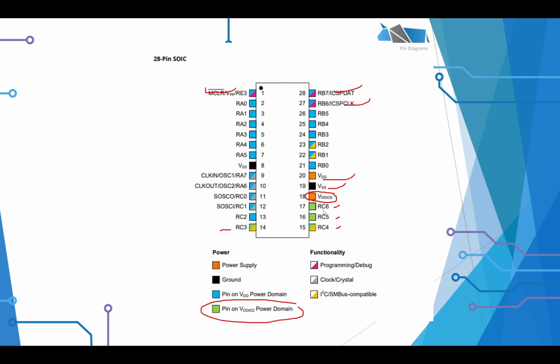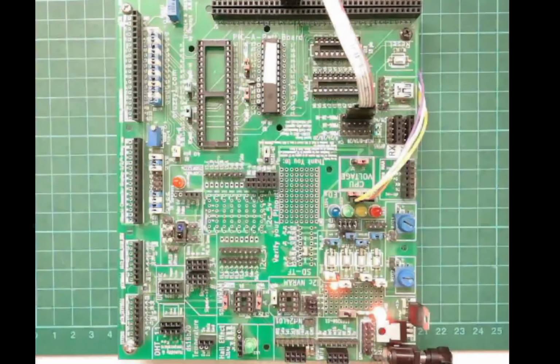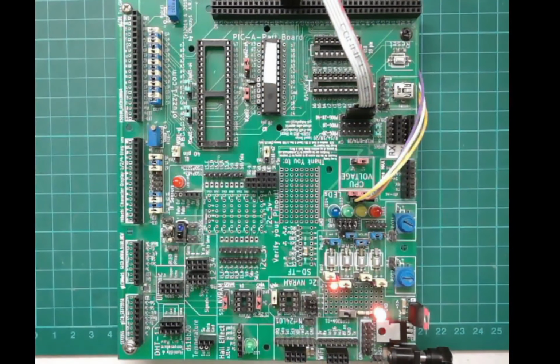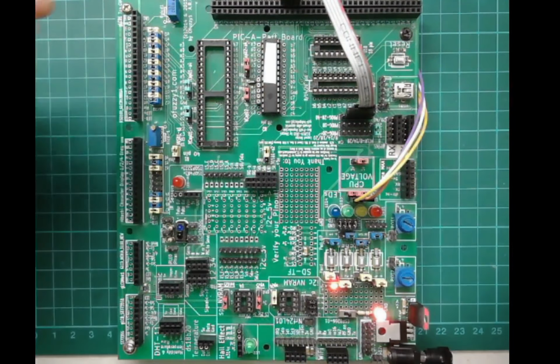It doesn't exist. So I am not going to expect the LED on RC7 to work here, because that was where RC7 normally sits. So you just have to sort of trust me. I know that stuff off the top of my head. So RC7 is also the VDDIO2 input line. Once we know that, we're going to have to jiggle things around from the demonstrations that I was doing previously using those 4 IOs.